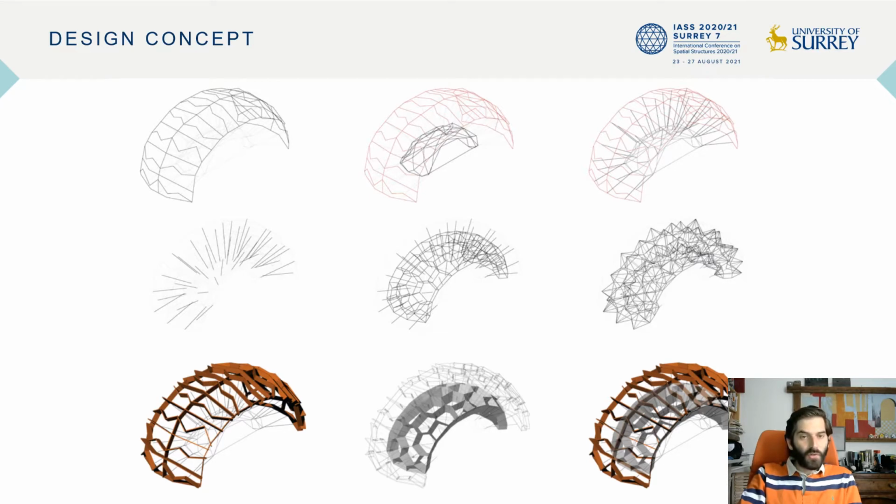The structure consists of an outer layer of birch plywood members pulled inwards with wire ropes. Rope ends connect at a triangulated mesh of wires in tension. The internal mesh is being stressed at the end of the assembly and then pulls the outer 38 cables connecting to the beams. Force is carried through a combination of bending and torsion in the outer beams and through pure tension in the wires. This follows a nature-inspired philosophy of different types of properties in biological structures.